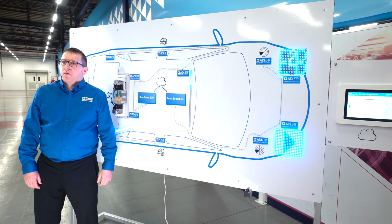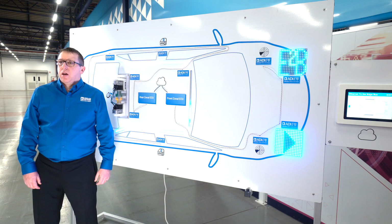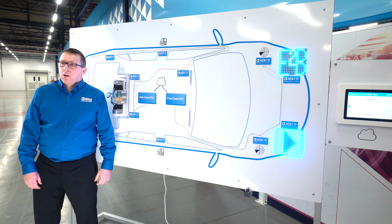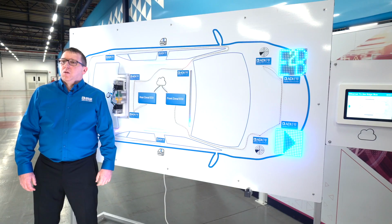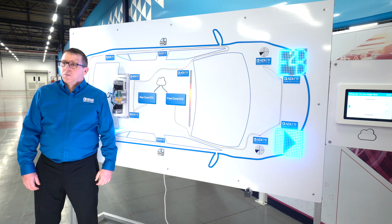E2B incorporates a fully compliant 10BASE-T1S IEEE 802.3 CG Ethernet PHY, as well as the MAC supporting point-to-point and multi-drop format. The bus operates at 10 megabits per second over single unshielded twisted pair cabling. In addition to this, it includes ADI's low complexity Ethernet technology, which enables removing the MCU and software on edge nodes to achieve a complete hardware solution. All software can be centralized back at the zonal or central ECU.